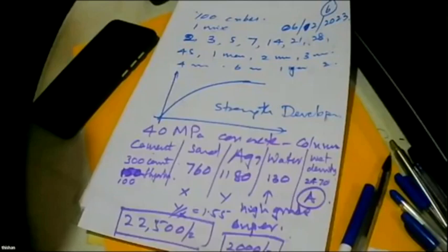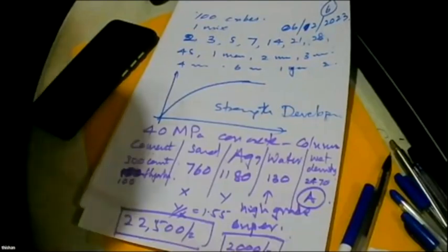Then Engineer Ekanayake asks, how about the steel structure with this hollow pole? What is that? That hollow pole? That is pre-stressed concrete. It's not reinforced concrete. That's why they wanted 65 megapascal in 24 hours to do the debonding. So it's a pre-stressed concrete pole, a stress pole, so it's very strong. You would have seen these used by Sri Lanka Telecom.